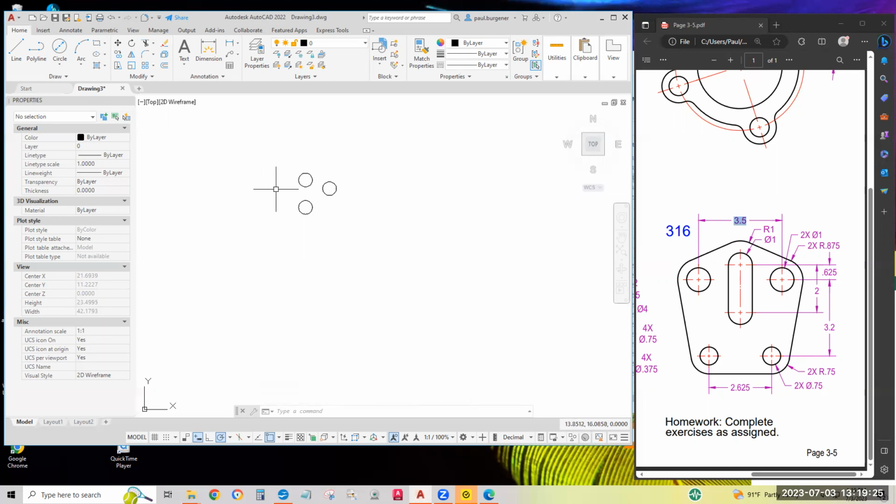Okay, this circle here can be a mirror copy of that. What the heck? Let's make it now. Copy that, mirror line, and enter. There we go. To make the arc across the top right here, let's start with a circle of radius 1. Now click circle, center radius, snap at the center, 1.